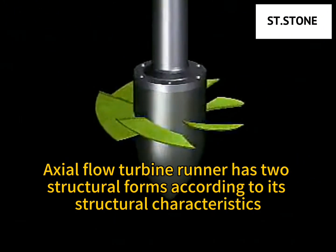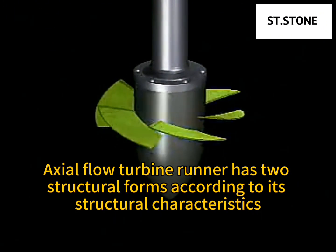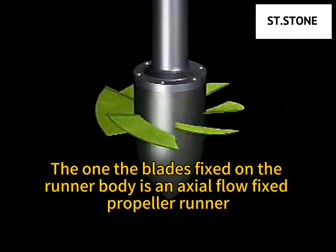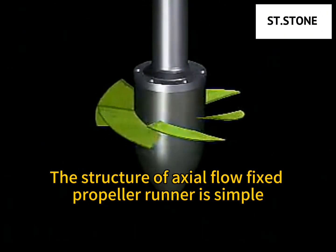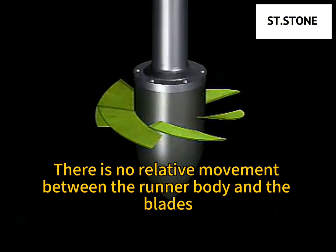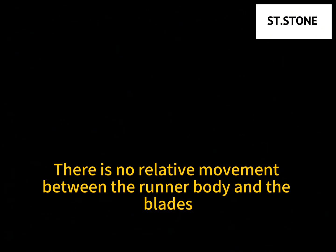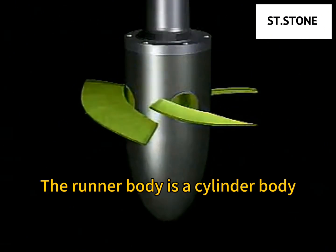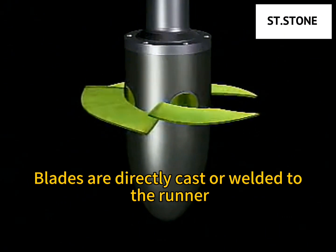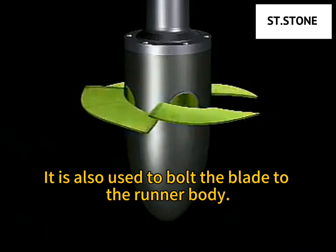Axial flow turbine runner has 2 structural forms according to its structural characteristics. The one with the blades fixed on the runner body is an axial flow fixed propeller runner. The structure of axial flow fixed propeller runner is simple. There is no relative movement between the runner body and the blades. The runner body is a cylinder body. Blades are directly cast or welded to the runner. It is also possible to bolt the blade to the runner body.